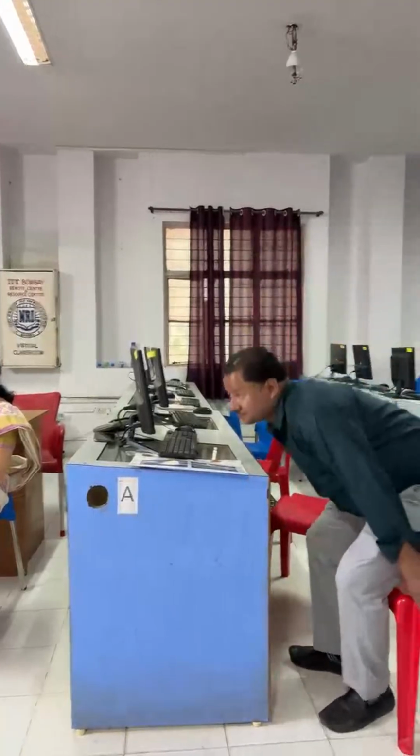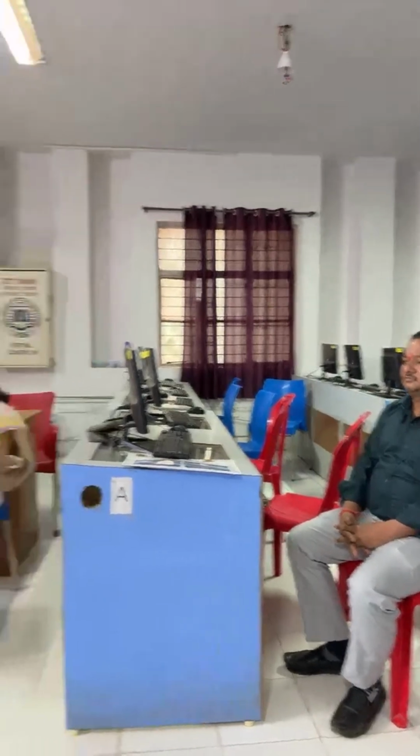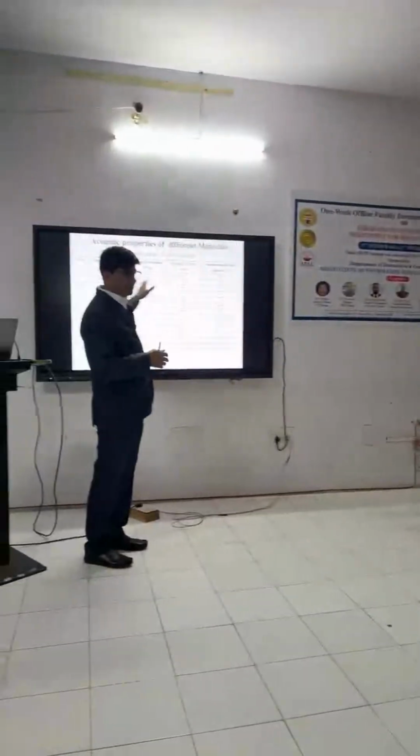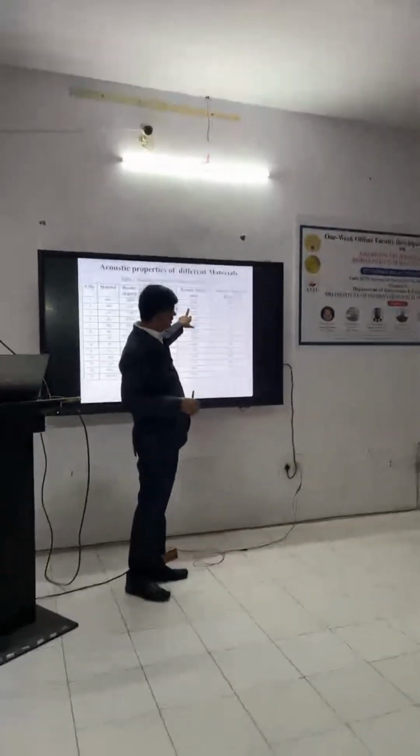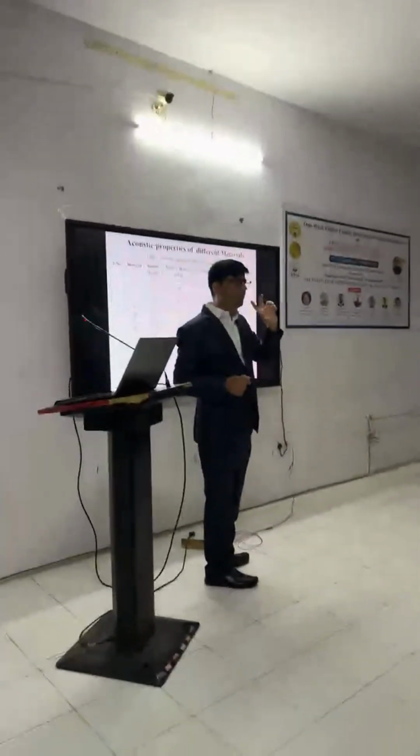If we want some gigahertz, for that we have piezoelectric materials, aerodynamic materials, so many smart materials nowadays. So you can optimize that material also. Are these all works only up to kilohertz? No, gigahertz. Yeah. See, if we calculate this with the acoustic velocity, for example, if I select 1 micron thickness of my aluminum nitride,